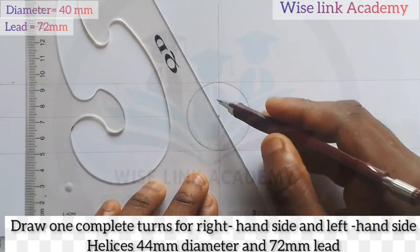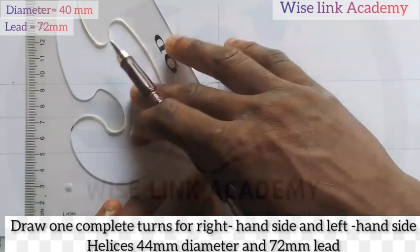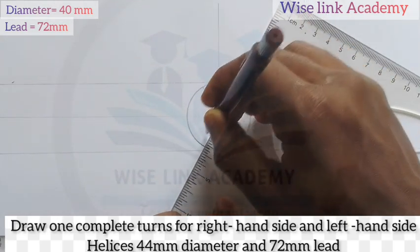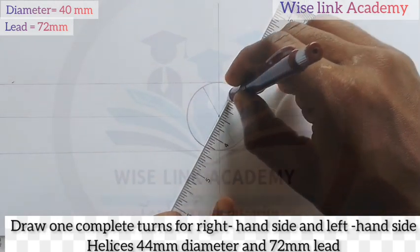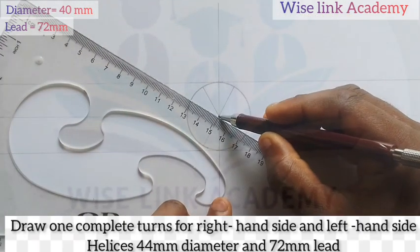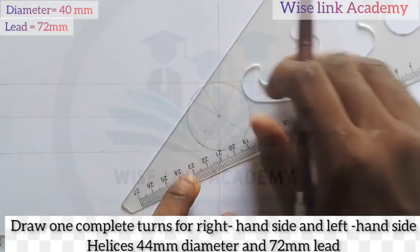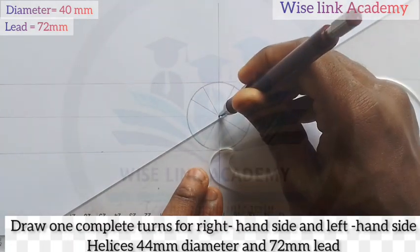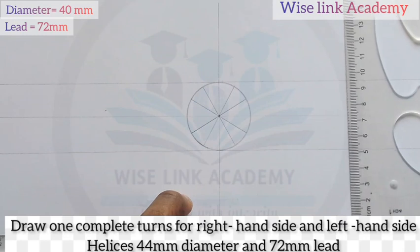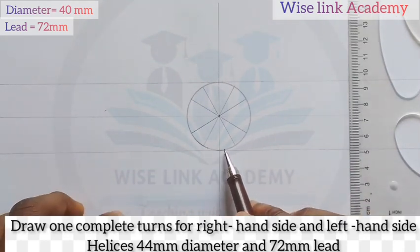I'll take it this way and draw it down this way. Similarly, I'll take it this way, and from that point, I'll draw it down this way. As you can see, next up, take it down this way, connect this point to touch the circle, and take it round from that center point to touch the circumference of the circle. Now, we have successfully divided this circle into 12 equal parts.